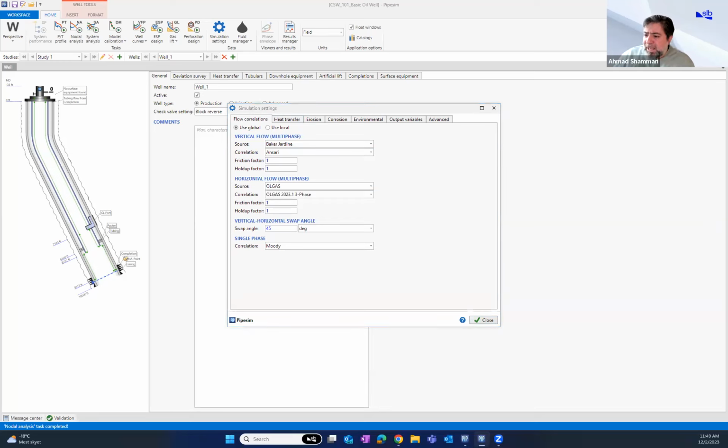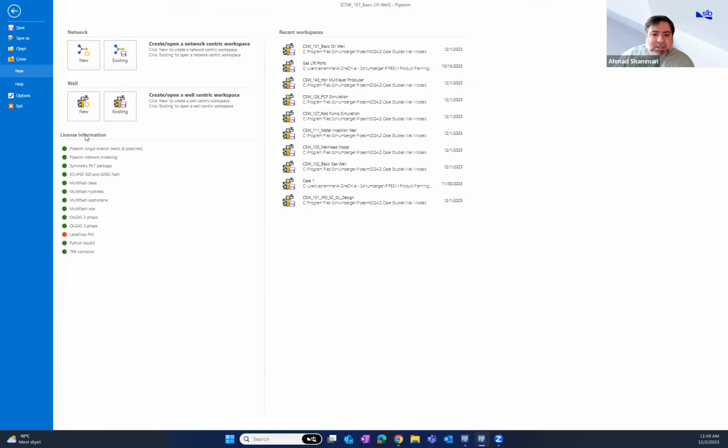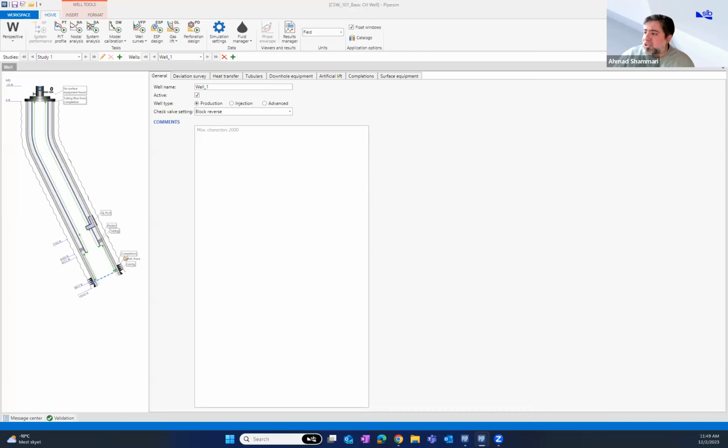Other question, can we do the same to check the gas lift is working properly or not? Let's say detect multi-point injection. So yes, exactly. So this is what I showed you before. When you enable multi-point calculate, because look, if you have one of the gas lift cases where you're using an injection valve system, let me show you here. Like this case, for example.